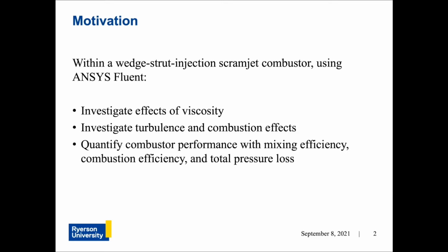The effects of turbulence should occur behind the wedge base, which is normal to the main flow, since an adverse pressure gradient is expected, generating a wake region. With the injection of hydrogen, a recirculation region should form, and the change in turbulent effects is compared with the implementation of a combustion model. The combustor performance can be evaluated by mixing efficiency, combustion efficiency, and total pressure loss. These parameters are heavily influenced by the formation and strength of shock waves, as well as the dissipation of turbulent eddies